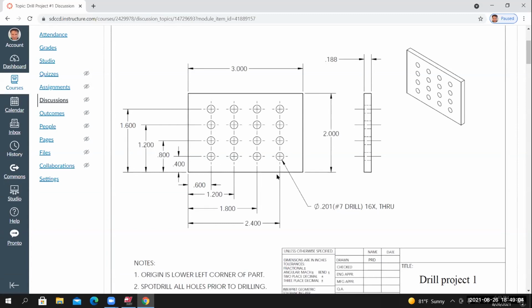along the x-axis. Before I do that, though, I need to verify that the spacing from center to center is the same between these four columns. The distance from the center of this hole to the center of this hole would be the difference between this dimension and this dimension, 0.6. You guys see that? Yes. The distance from the center of this circle to the center of this circle would be the difference between this dimension and this dimension. Once again, it's 0.6. You guys see that? Yes.